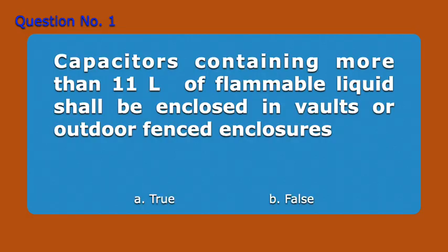Question number 1. Capacitors containing more than 11 liters of flammable liquid shall be enclosed in vaults or outdoor fenced enclosures. A. True. B. False. Answer: A. True.